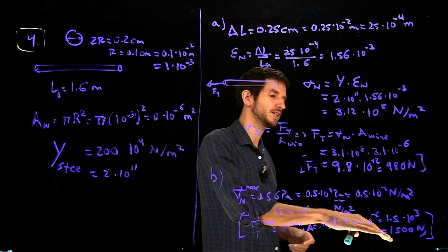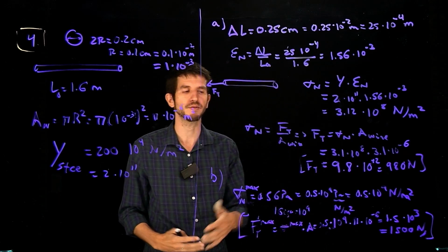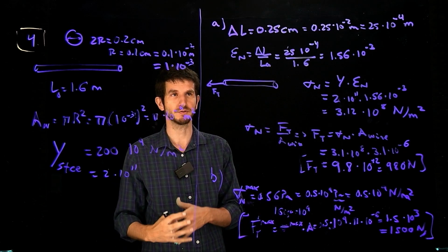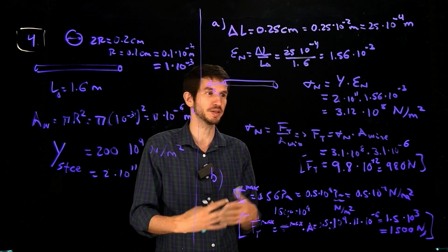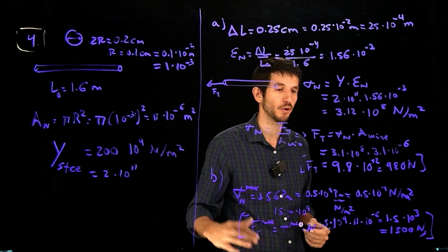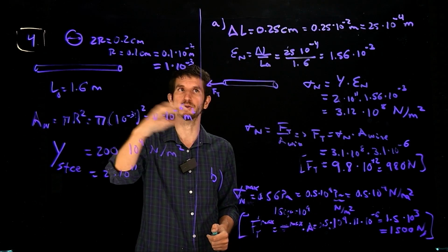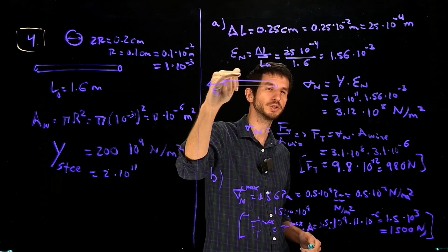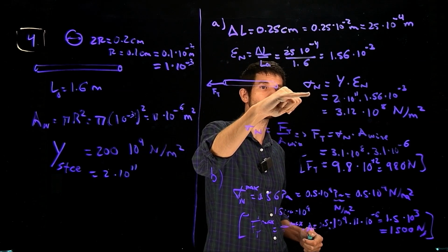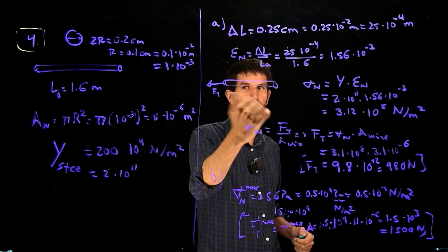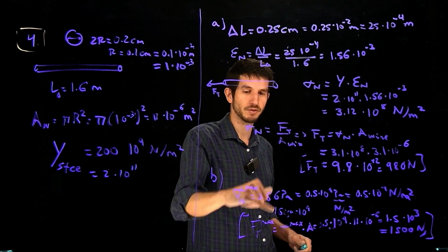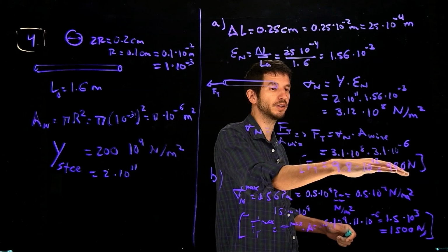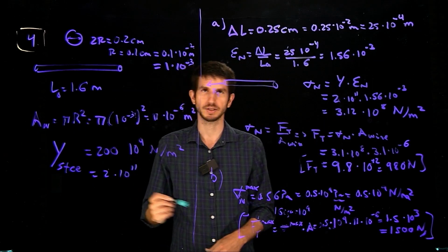But in this case, if the maximum is 1500 and the answer is about 1000, then yes, we are safe, or there's nothing safe because it's a piano, but basically the piano string is going to hold. Okay, so here again we see how we deform solids because we produce a deformation. Because we produce a deformation, this creates the stress. The stress eventually is just the result of the force, in this case tensile. And if the maximum tensile force that we can apply is 1500 and we're having here 1000, we're all safe. Let's see more examples.